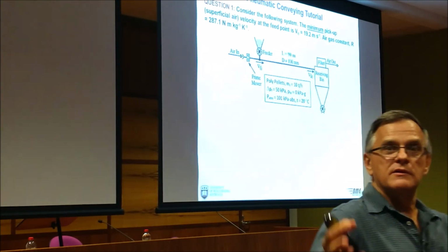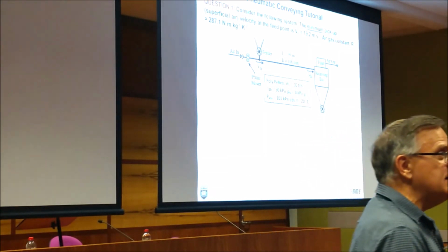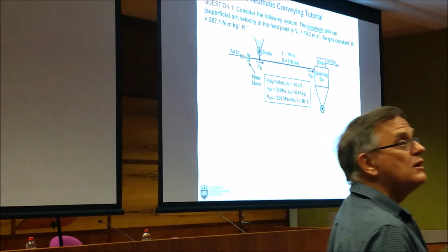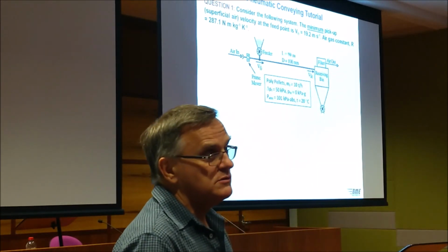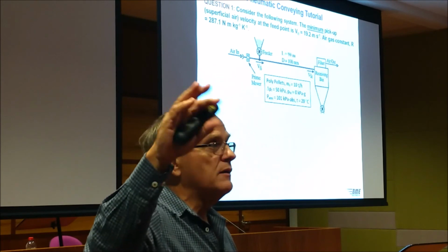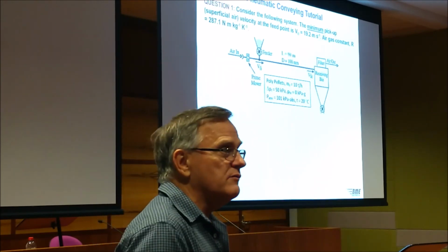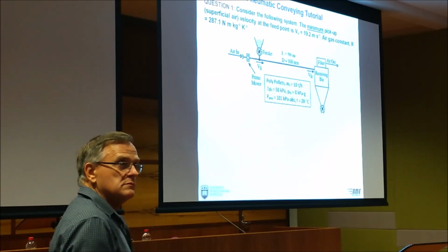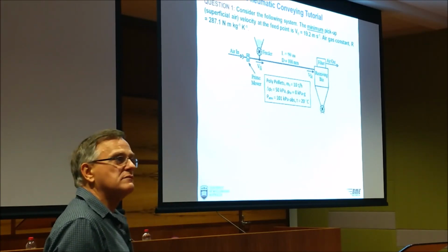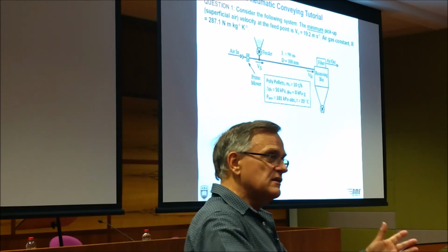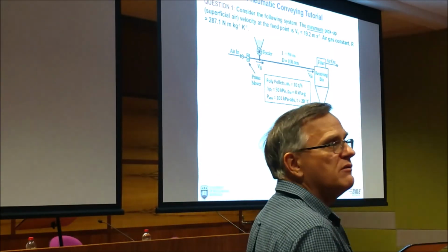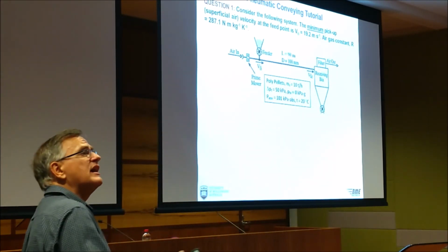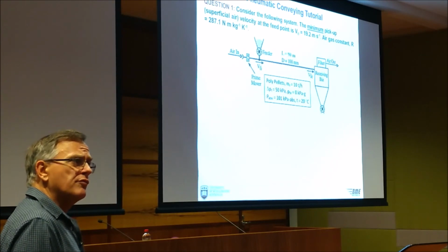Atmospheric pressure, what do you reckon? Have you checked your barometric readings today? 1010 hectopascals is the correct term we use for atmospheric pressure, which is 101 kilopascals. It goes up and down depending on what cyclones are around and low pressure systems, but average 101 typically at sea level. If you get 1 kilometre above sea level, it's different. But at sea level, we use 100, typically. So at atmospheric conditions, the gas density is about 1.2.